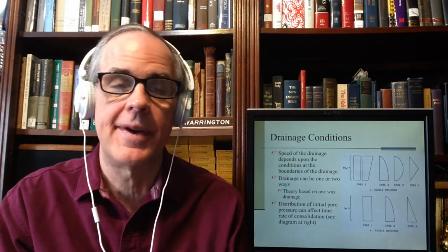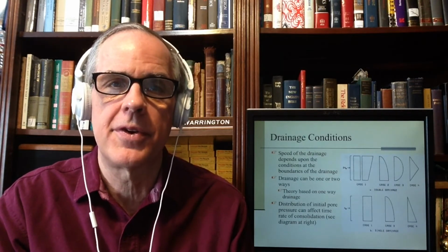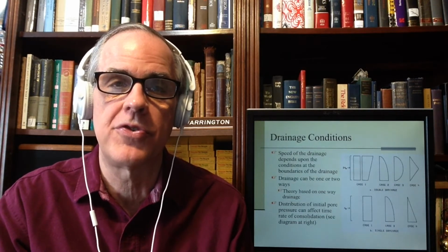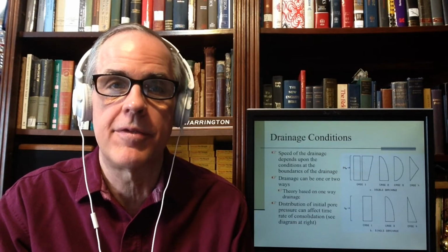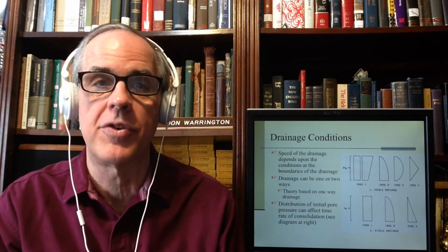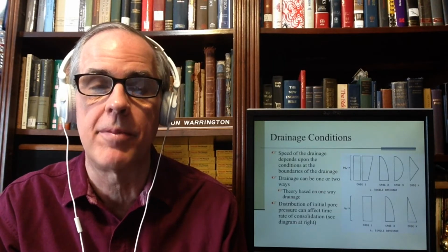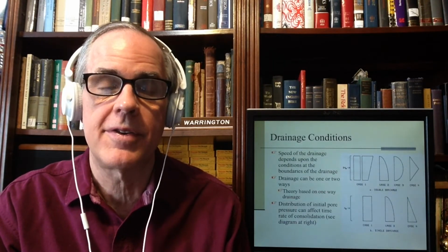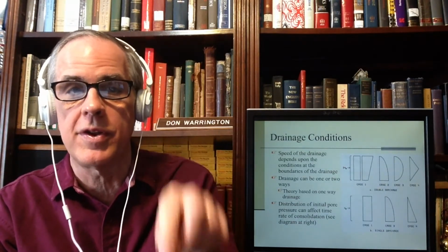Now you say, well, pervious, impervious. Pervious, that's a relative term. I'd be the first to admit that, but I also showed you in permeability that permeability can vary and does vary between soils by several orders of magnitude. If you've got a clay layer with a sand layer above it and rock below it, it's pretty easy to say that for practical purposes, above is pervious and below is impervious.